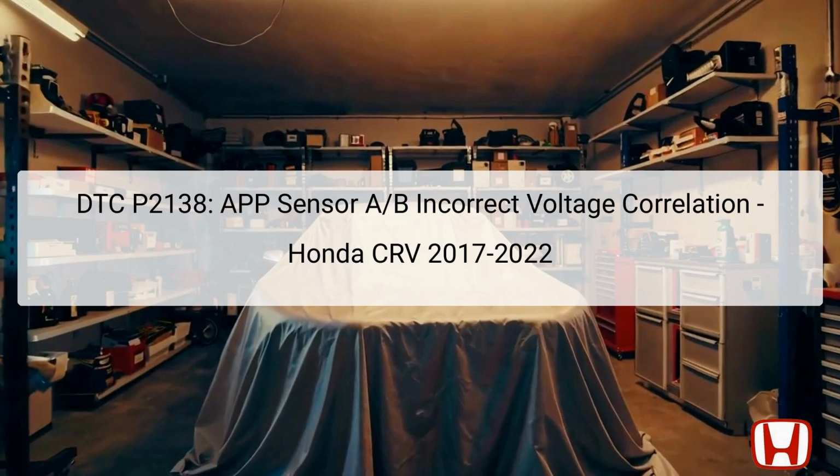The Diagnostic Trouble Code, DTC P2138, refers to an issue with the accelerator pedal position, APP sensor A and B, specifically indicating an incorrect voltage correlation between these two sensors. This code is often seen in vehicles equipped with a direct drive accelerator pedal system, using sensor inputs to communicate with the powertrain control module, PCM.